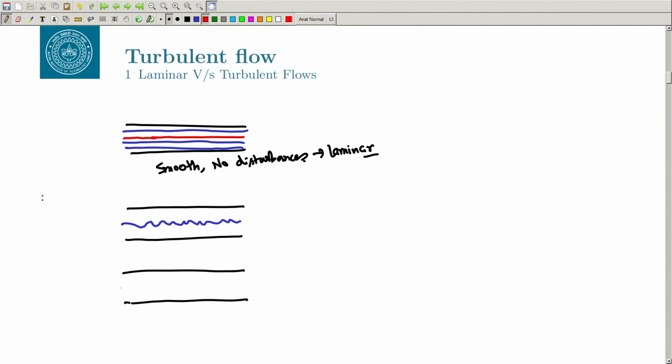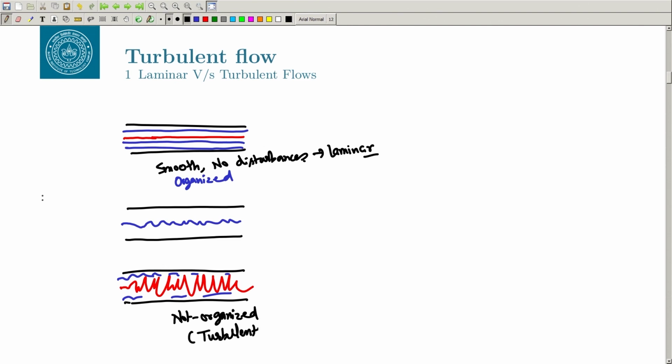and then what he found is that now there is so much zigzag, so much disturbance all over. Okay. They are not basically staying in line. Okay. So, you can see that now they are no longer very organized as we had earlier. So, this was an organized flow on the top, and the flow at the bottom is basically not organized, okay, very violent, there is mixing all over everywhere, right. So, he termed this flow as the turbulent flow, okay, because it is turbulent, right. This is laminar, this is turbulent, and in between you can have flow which you can call transitional flow.